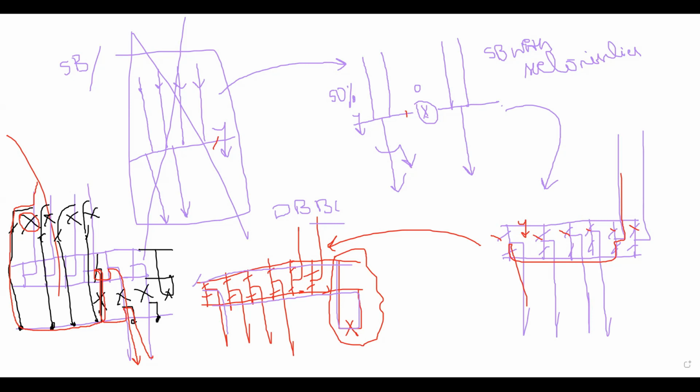And apart from this, we have one more scheme, which we call the 1.5 breaker scheme. In the 1.5 breaker scheme, we have two buses and three breakers like this. Three breakers, and we have two lines, one line, the other line, this line, and these are the four incoming lines and these are the two outgoing lines.